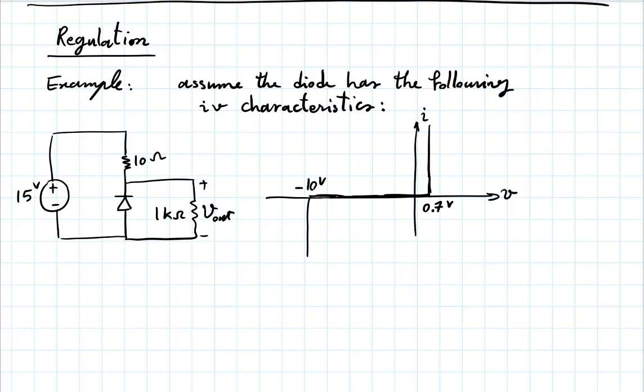and that would require a positive current, any positive current, right? It can have 0 current as long as its voltage is between 0.7 positive and minus 10. And it can have a fixed minus 10 volt as long as its current is negative. So you just have to try these 3 possibilities of where the diode is on its characteristics.